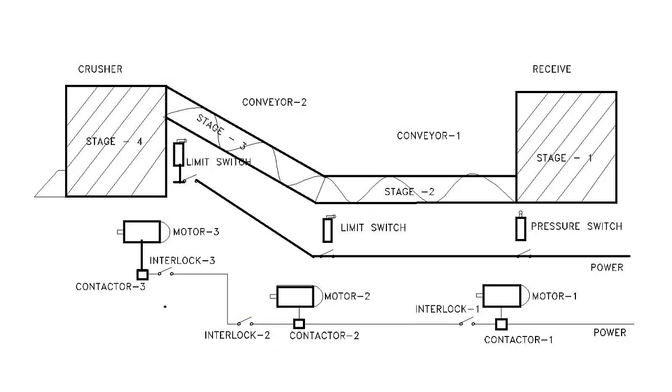Rocks move through conveyor 2 and when it reaches the crushing station, limit switch 2 closes and sends power to contactor K3. When K3 closes, the latch associated with it also closes to hold the contactor continuously. The crushing station starts its process of crushing the rocks.